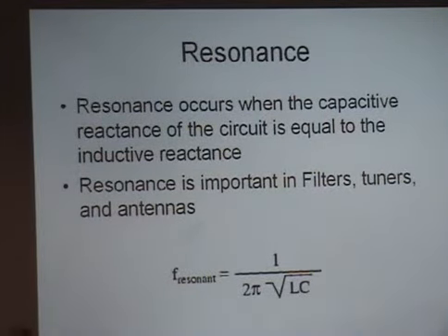It will look rather like this. If you think of your AC source over here as your RF output from your radio, it would be hooked through that 100 millihenry coil, and then your 10 microfarad capacitor is your antenna. But for this application and for this resonance, I think it's 159 hertz. So those numbers are nothing like what you're going to have in a real antenna system. This is just an example that I stole. And I thought about working it out, and I went, not quite yet. We can do that later.